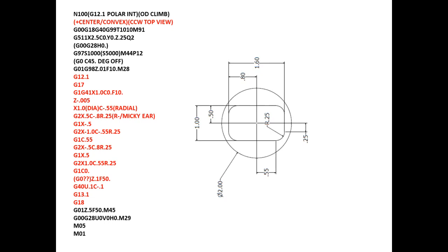Which means your geometry offset, your live tool center, is not set correctly. For example, if your center is above the center, you will have a convex shape. If your geometry offset is below the center somehow, you will have a concave shape. So you've got to have this perfect center line, then you will have a nice flat along the wall side.